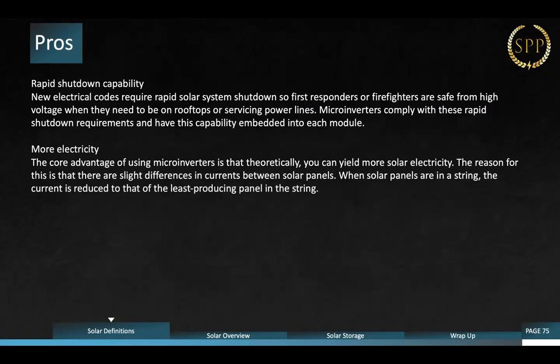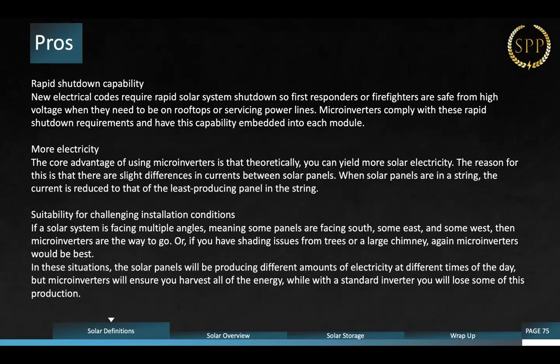So if you have 10 panels, the first 5 are operating just fine, then number 6 is causing a problem, then only the amount of power that's being sent through 6 is what's going to be in the rest of the system itself. With microinverters, you don't have that problem. Every panel works independently. So we like to say there's independent systems and there's string systems when we start having these conversations with the customer, because yeah, these can be pretty great systems.